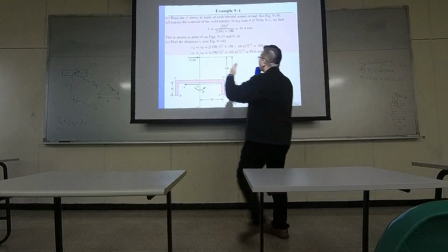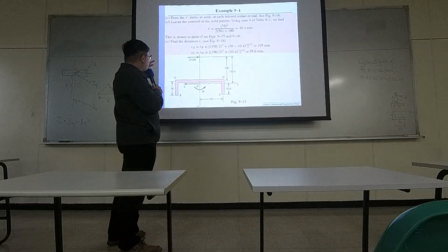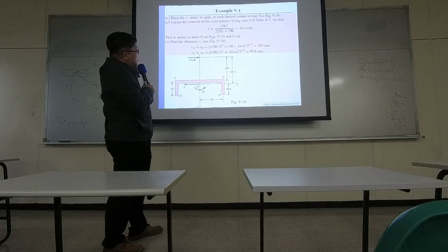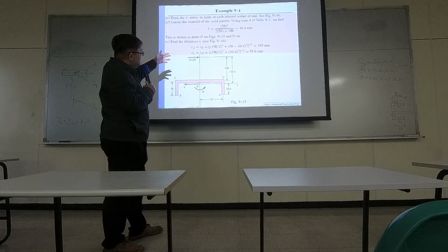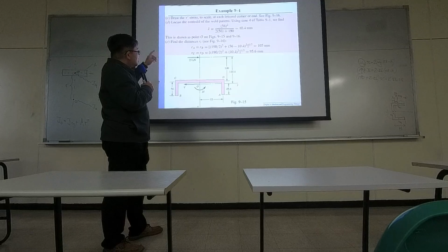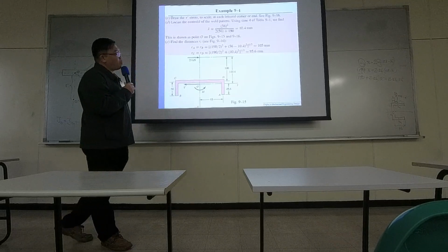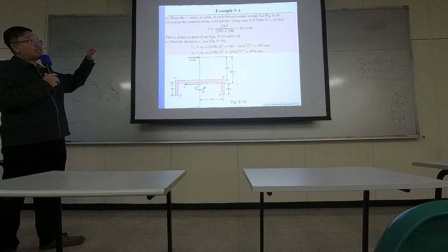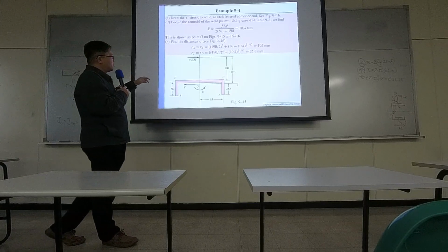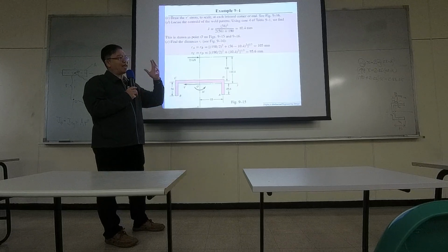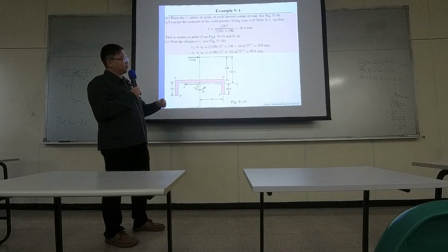So once you have X bar, the rest are simple. You are just going to compute the radius. And why does this textbook example show you the radius for A, B, C, D corner points? Because that's where you have the most probable positions that have the greatest shear.